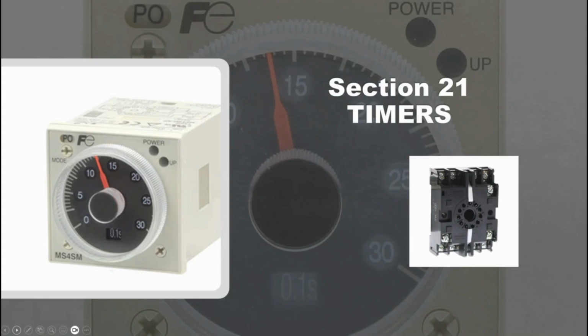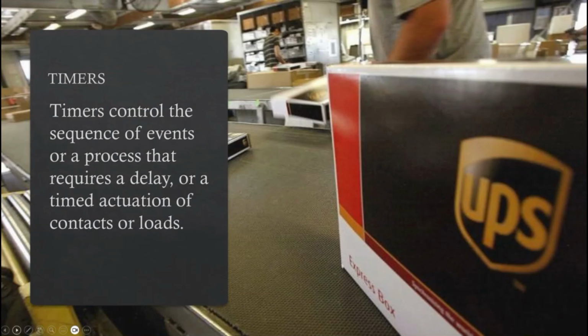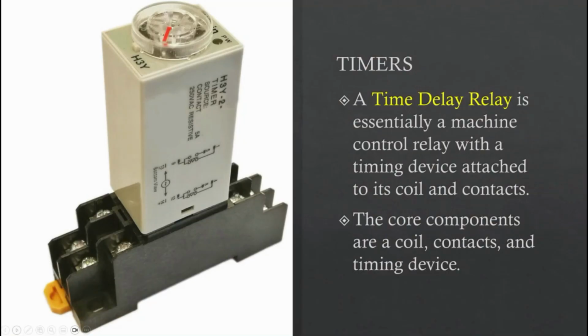Section 21, timers. Timers control the sequence of events or a process that requires a delay or a timed actuation of contacts or loads. A time delay relay is essentially a machine control relay with a timing device attached to its coils and contacts. The core components are a coil, contacts, and timing device.